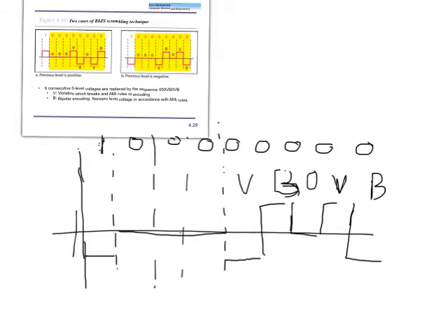So by doing this, what I essentially did is that I avoided the consecutive 0 voltage, which was causing a problem, okay, by creating different voltage levels. So the change in the voltage level will definitely enhance synchronization, right? So instead of having constant voltage level of 0 for 8 consecutive bits, I created some kind of change which essentially enhanced the synchronization. But it's always in this order.